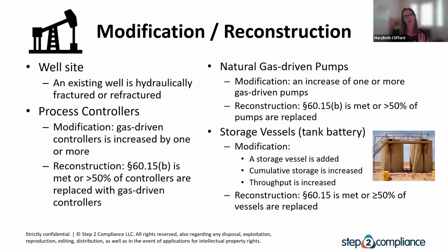Storage vessels, this is where understanding the difference between modification and reconstruction is important. Modification: if you add one vessel, or you increase your throughput, or you increase your cumulative storage, or if you swap a vessel and put in a larger vessel, that triggers modification. Reconstruction is triggered when you replace 50% or more of the vessels that are there.